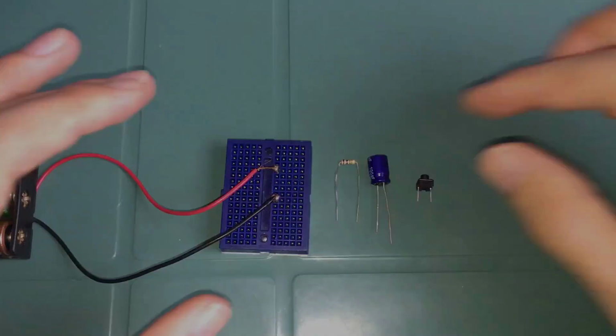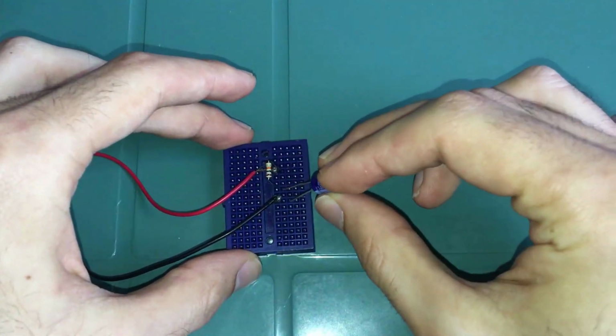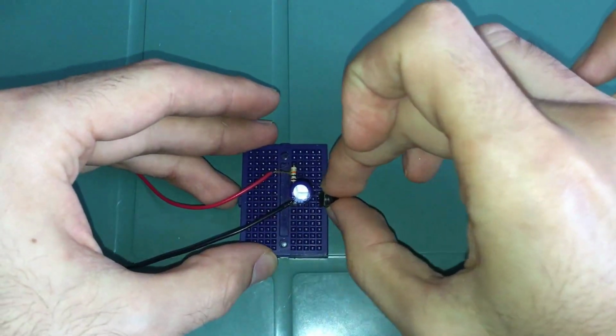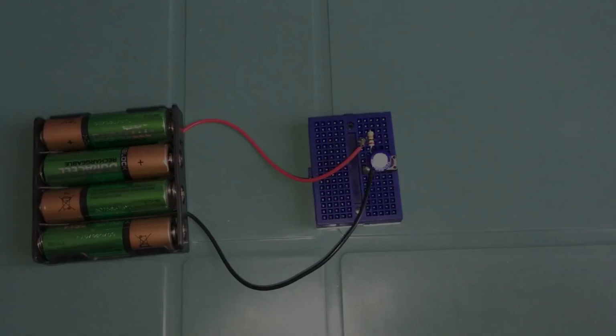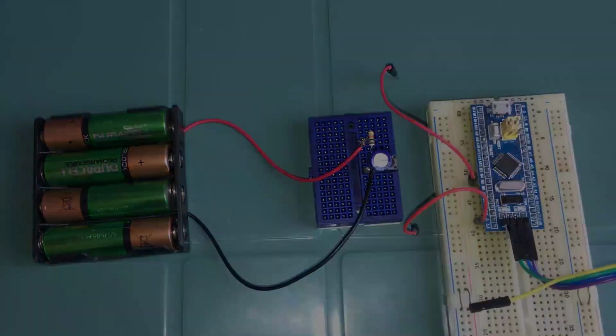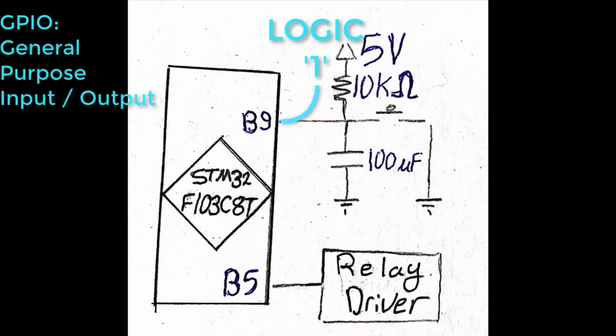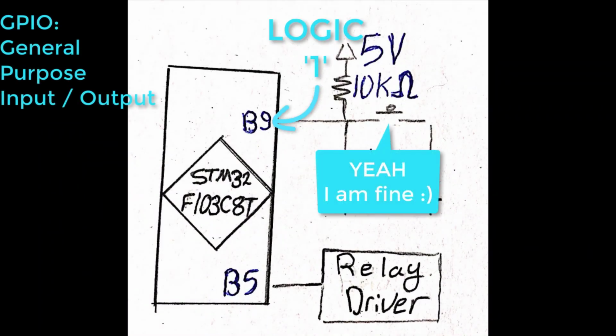As I had promised, in this video, I will be talking about the circuit I used for triggering a falling edge event by the microcontroller. Although it seems simple, let's see what the theory tells us. When connecting this circuit to a GPIO pin of a microcontroller, the controller will read 1 as long as the push button is at its normal state.